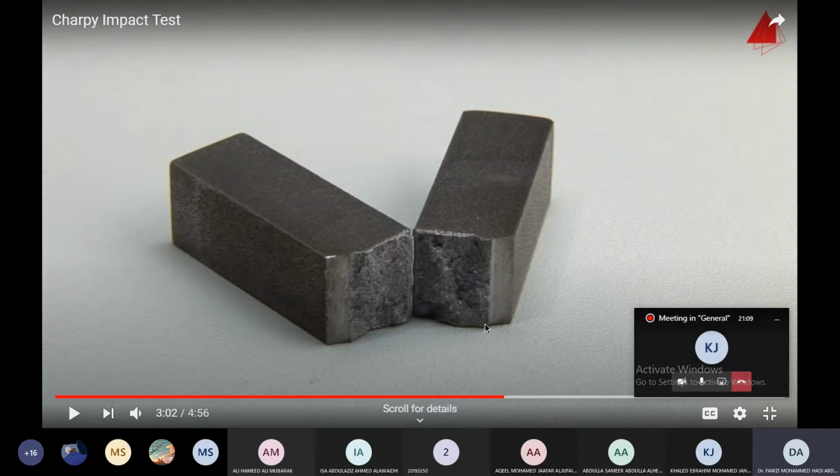It has some deformation there, but like when we talk about carbon, when we increase the carbon content in our steel, what does it do? Of course, even the 0.8% carbon steel is not a brittle material because it has a good appreciable amount of plastic deformation happening there. But what we say is it embrittles. Embrittles means it's going towards brittleness, as we increase the carbon content. Here now, when you strain age the material it embrittles. This is what she is saying here.